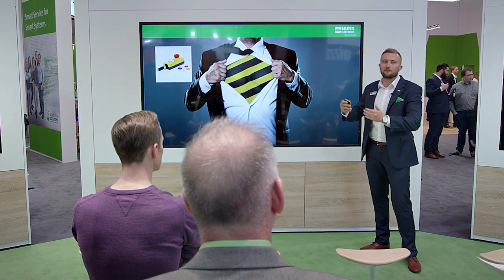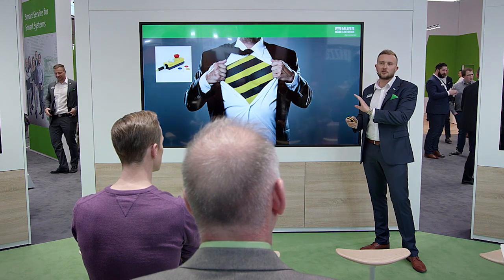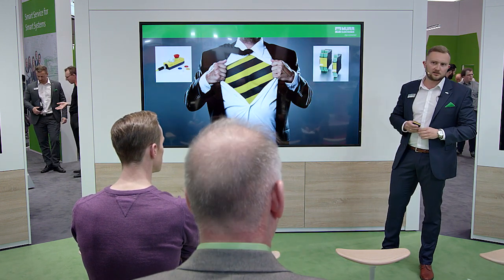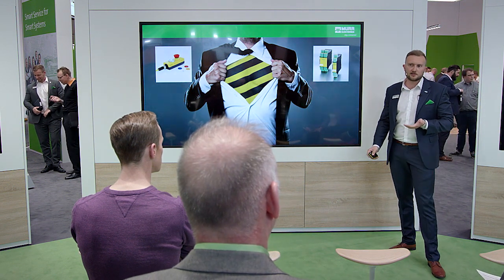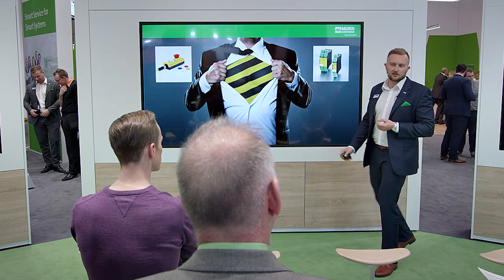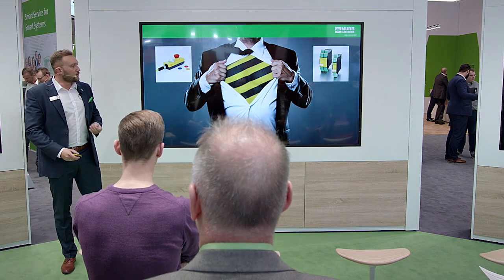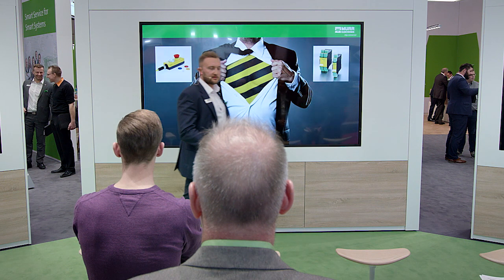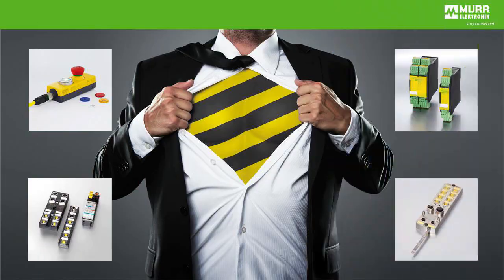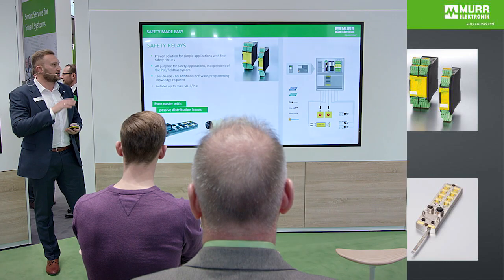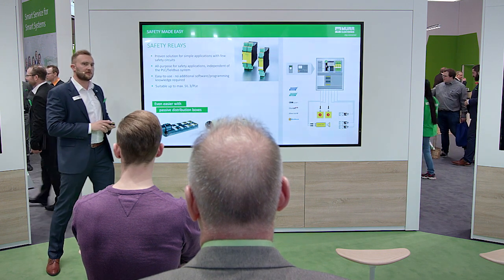But when we go one step further from the sensors, then you have some logic. And the most popular solution, I guess, would be a safety relay. I think still 60-70% of safety applications are realized with safety relays. And then another step, which is getting more and more popular, are safety I/O devices, either passive safety devices or active safety devices. I would like to show you today three installation safety concepts with Murrelektronik products to make your safety installation easier. The first topic is a traditional solution based on safety relays.